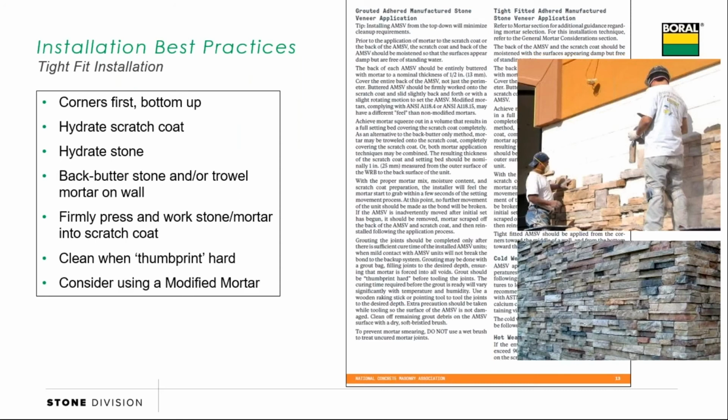Let's talk about tight fit installations. This is a very popular look. We don't see that changing anytime soon. Our recommendation is lay your corners first. I was fortunate, the guys that trained me were natural stone, brick, and block guys. And so we would lay our corners up first, start at the bottom, and lay our stones back and forth in courses. These guys did a little bit of that, but then they created themselves a hole.